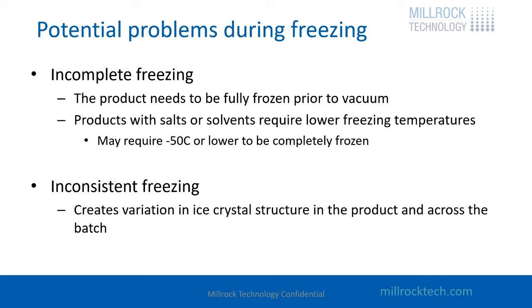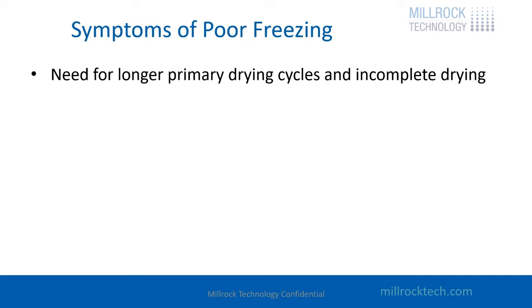So it's highly recommended that you freeze in the freeze dryer when you can, and it's done at a controlled rate so you get consistent ice crystal structures across your batch. Symptoms of poor freezing. Poor freezing can lead to longer primary drying cycles and incomplete drying.